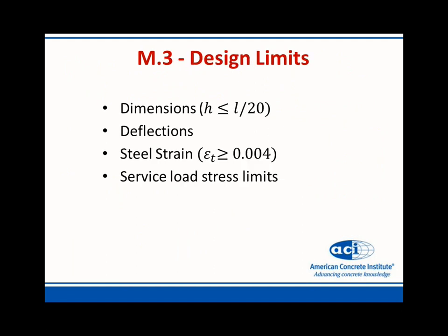M.3 addresses any design limits that apply to this particular member. Could be dimensions: the depth of the member has to be less than or equal to some value. Deflection limitations, any limitations on the steel strain, and any service load stress limits that apply.